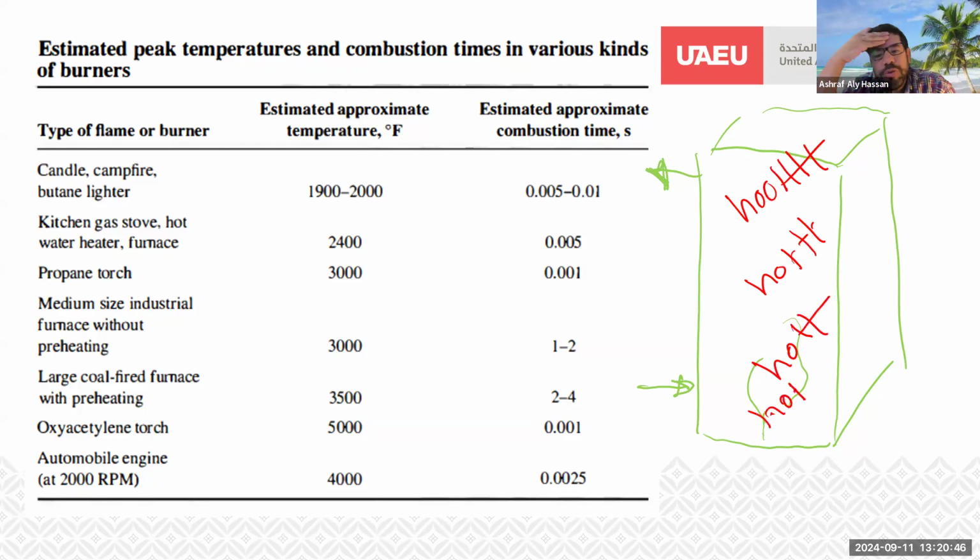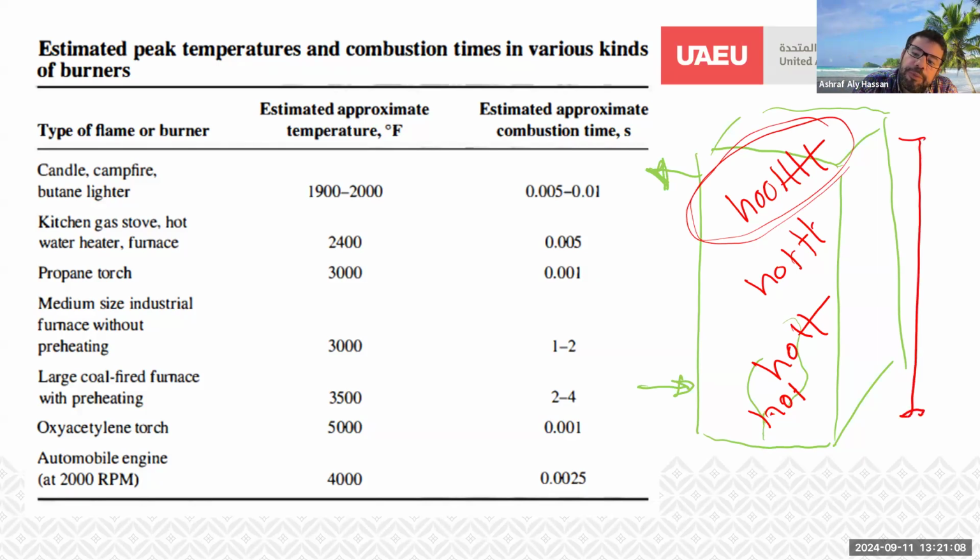So when we are calculating the actual flow, we are calculating it based on this temperature, which is not really fair for the time, because we have a gradient of temperature as we talked about earlier. Additionally, the gas does not really travel the whole length of the boiler.